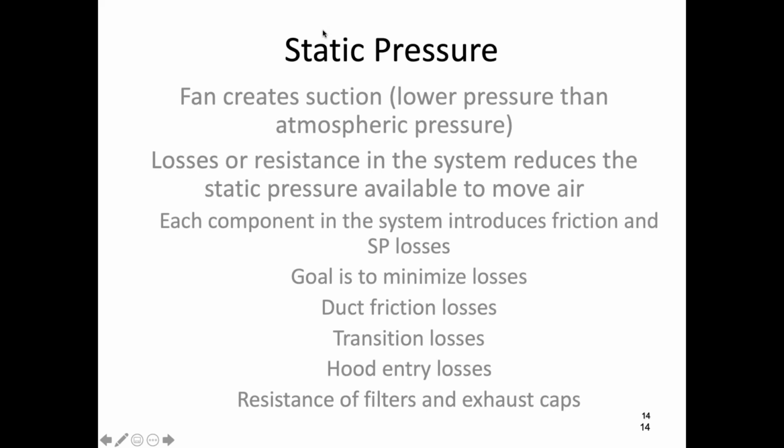We have a fan going, it starts to suck air, it's connected to ductwork. What's it going to do? It's going to start to suck air through that ductwork. So what velocity are we going to generate in that ductwork? It's going to depend on the horsepower of the motor, the amount of static pressure that we generate, the amount of friction in the ductwork as it goes through, the number of turns that contribute to the friction, and so on and so forth.